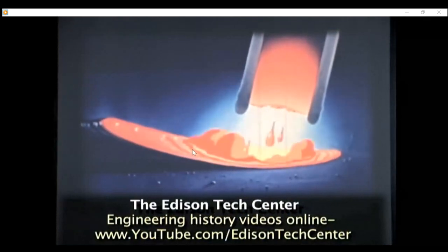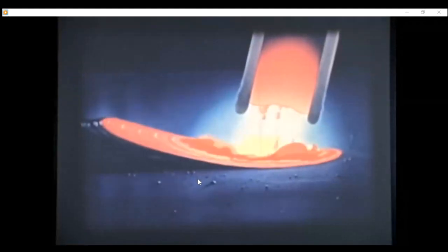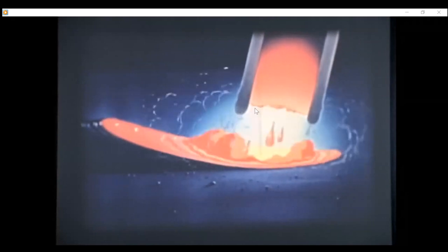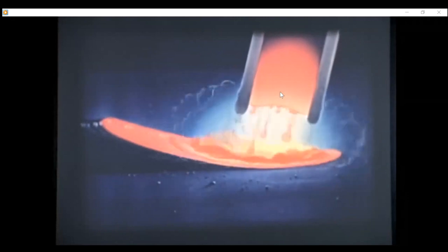This is the same material. You must remember that this kind of arc welding, or generally fusion welding, is limited to similar materials, not dissimilar materials. So this is a filler, and it is a filler and electrode at the same time. And you see this is a flux, coated with the flux. This flux also melts and creates a gas. We call it shielding gas.